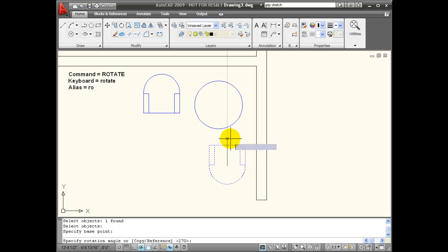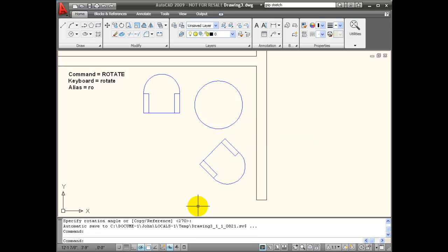And what I want is the chair turned 45 degrees from its current location. So I bring my polar angle over here to 0, and that's the current location. I bring it up so it locks in at 45. When it locks in at 45 degrees, I click the mouse and place the rotation of the chair. So remember that when you're using your polar angles, you're moving the chair relative to the number of degrees counted from the 0 point on your polar angles.